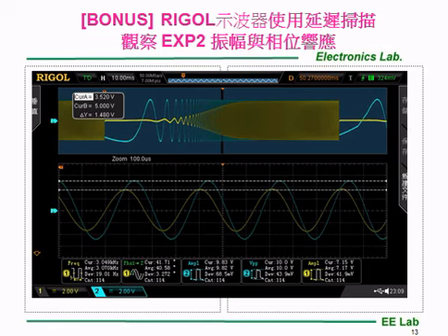Now, the bonus lab. Using the oscilloscope, we could also observe the phase difference in the above configuration, using the Rigol oscilloscope, giving you the following values. Note that in the Rigol oscilloscope, phase difference is always measured by signal 1 subtract signal 2. Therefore, the correct configuration is to make signal 1 be our output signal and signal 2 be our input signal.